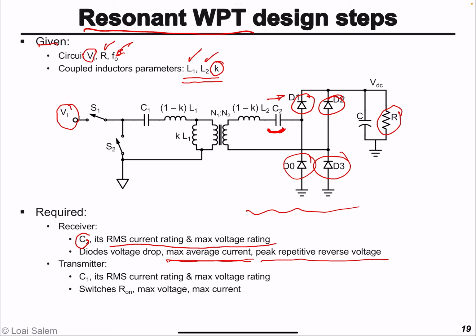And finally, of course, we need to select the output decoupling capacitor depending on the load, if it's a battery or just a pure resistive load. And in this case, we can follow a similar approach to how we calculated the output decoupling capacitance for a power supply.